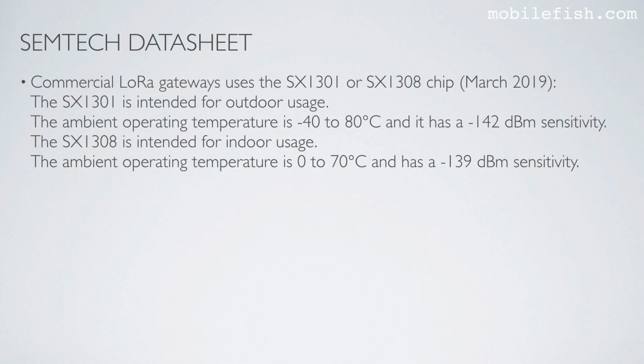Commercial LoRa gateways use the SX1301 or SX1308 chip. This video is made in March 2019. The SX1301 is intended for outdoor usage. The ambient operating temperature is -40 to 80 degrees Celsius and it has a -142 dBm sensitivity. The SX1308 is intended for indoor usage.